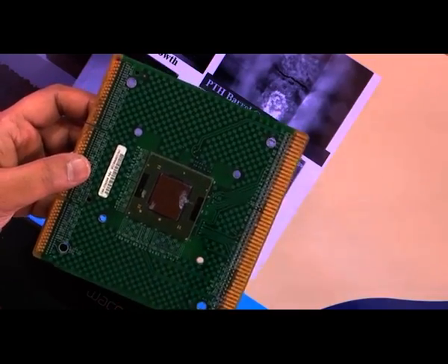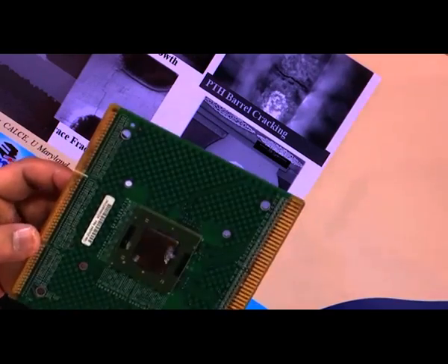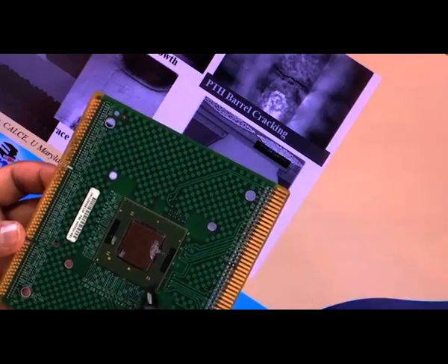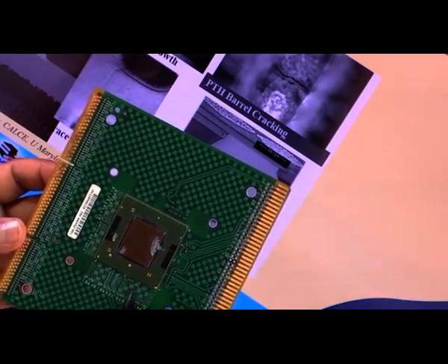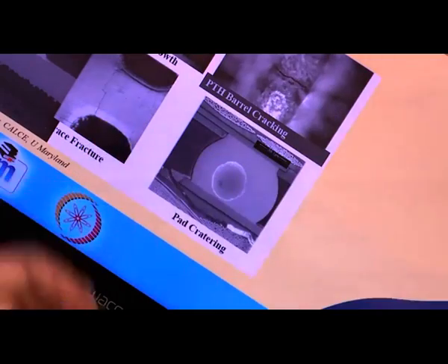Why? Because if we go back to our first level packaging, we talked about underfill epoxy. Silicon and FR4, because of the CTE mismatch, we use this underfill epoxy material, right, which results in reduction of the temperature induced stresses, clear. But why did we not have that between the package and motherboard? Because their CTEs are almost similar. So, why use it? Okay.